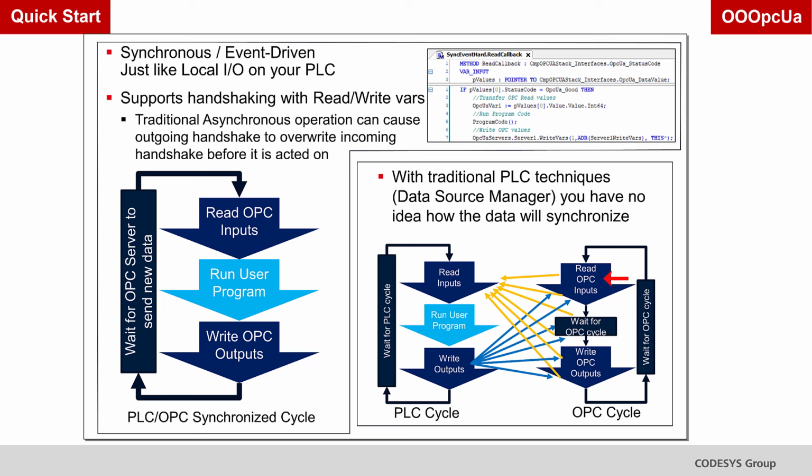The next OPC read cycle comes in and changes your false back to a true. The server never receives your handshaking confirmation and doesn't know it is clear to trigger another. So the system locks up, and it does so randomly. Sometimes your program writes the data in time to get it in the current OPC write cycle, and sometimes it doesn't. It appears to be a random bug.